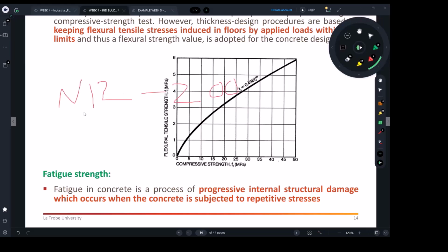This means your bars will be placed every 200 millimeters, and it's classified as N, which means normal ductility. You cannot go in a project and use a different ductility level, like maybe L type, low ductility. There is another type, L12. L12 means low ductility. Remember, on site, low ductility is cheaper, and maybe what can happen?